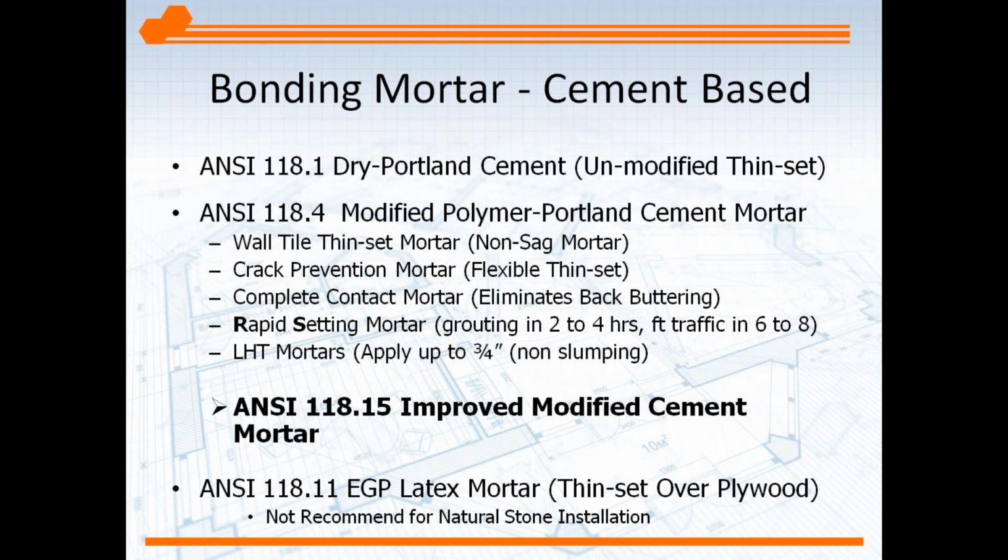The question I get a lot, and I may get some questions afterwards on this, is that ANSI does not make a mortar specifically called for large format tile. ANSI does not have a standard for LHT mortar. ANSI only has the standards for the bond strengths and performance characteristics of mortar. And you can buy the bond strength and characteristic in different mortars in an LHT version, is what I'm getting at. I hope that's clear. Maybe I can clarify that at the end if anybody has any questions. I may have been a little confusing on that.